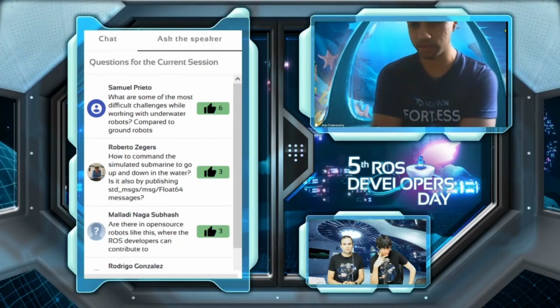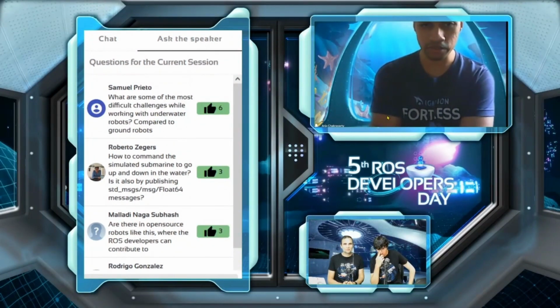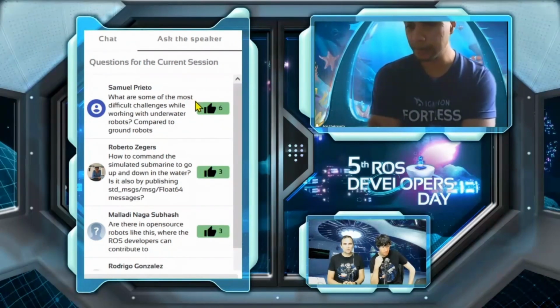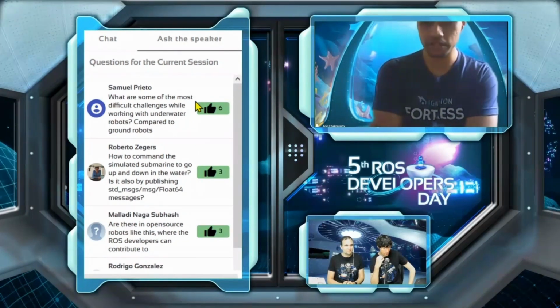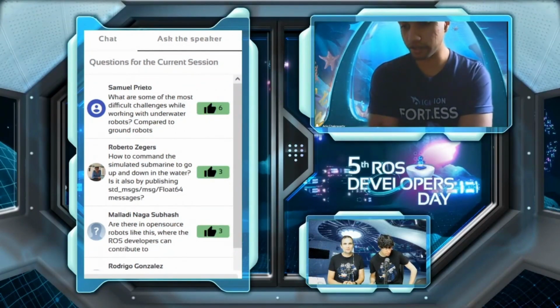The other big challenge, if you're doing hardware, is that mechanically it's hard to deal with. I've done some robots myself. It's a lot of leaks and stuff. Sensor suites are also very different. You have poor perception, so you would be using sonars, DVLs, a very different set of sensors than what we use on land. And also, you are mixing in simulation. I think the hardest part is the part which I showed you, which is getting the hydrostatics and hydrodynamics right. Those two are really critical to getting it right.